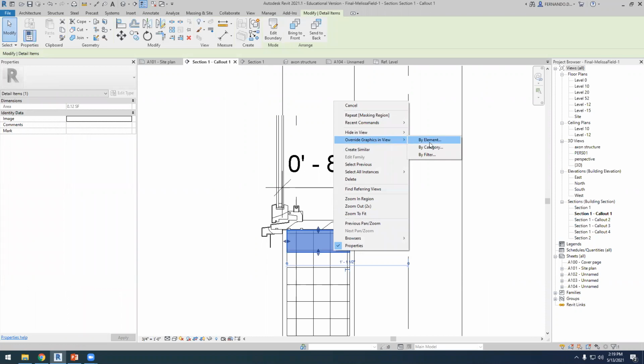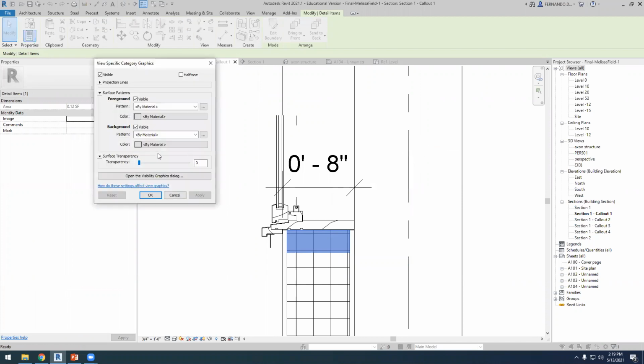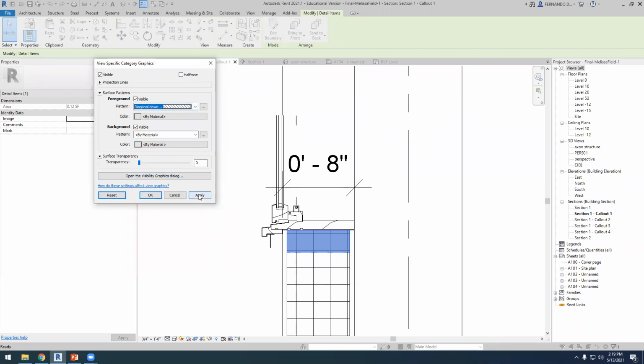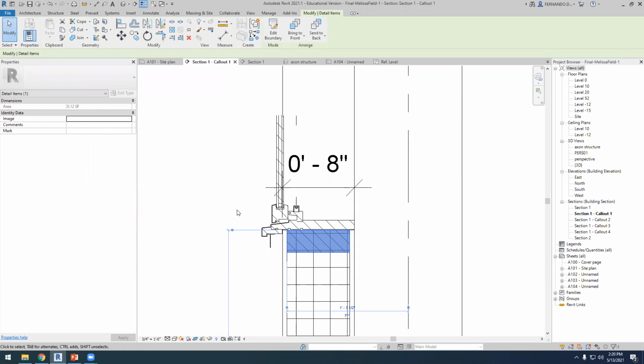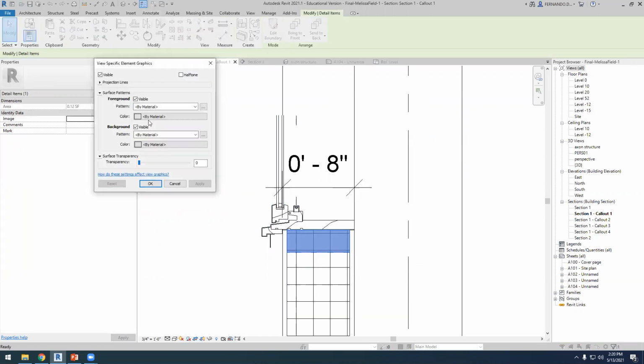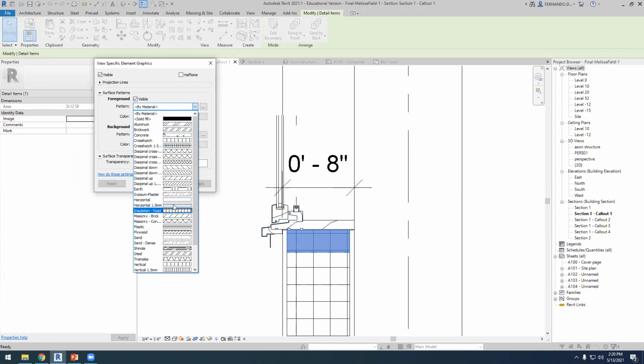Well, make sure that when you are defining different elements in the same element in different callouts, you are using the same hatch. Okay. We are using the projection line surface pattern. I will select this diagonal down. I don't remember. No, I don't want to do this. I selected category and I want to select element by element. And then material,